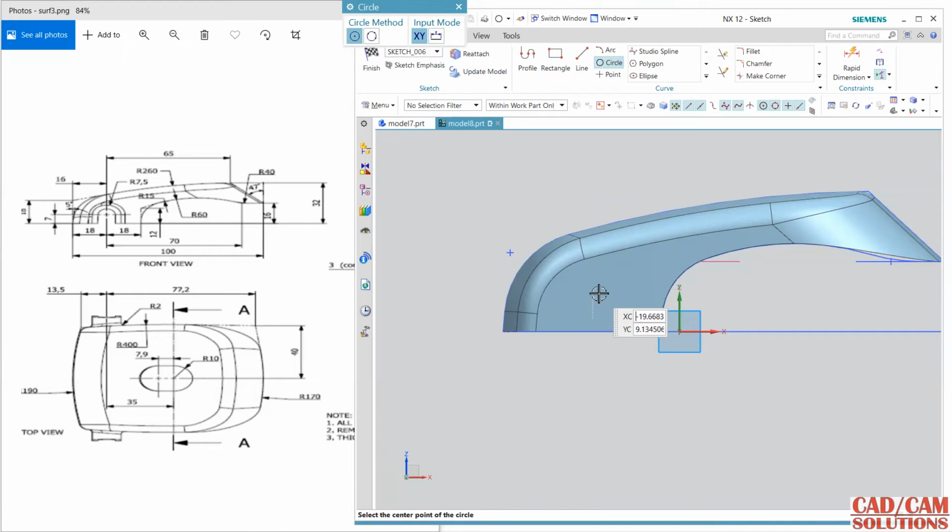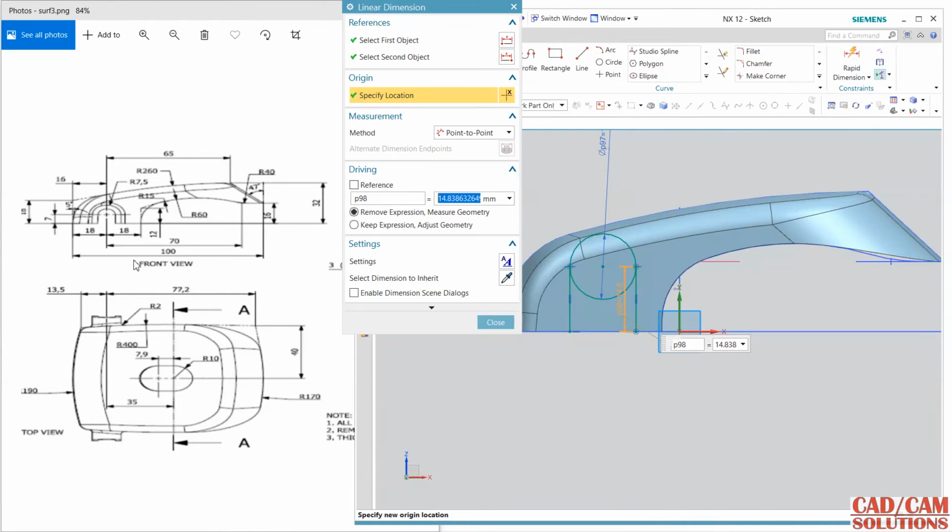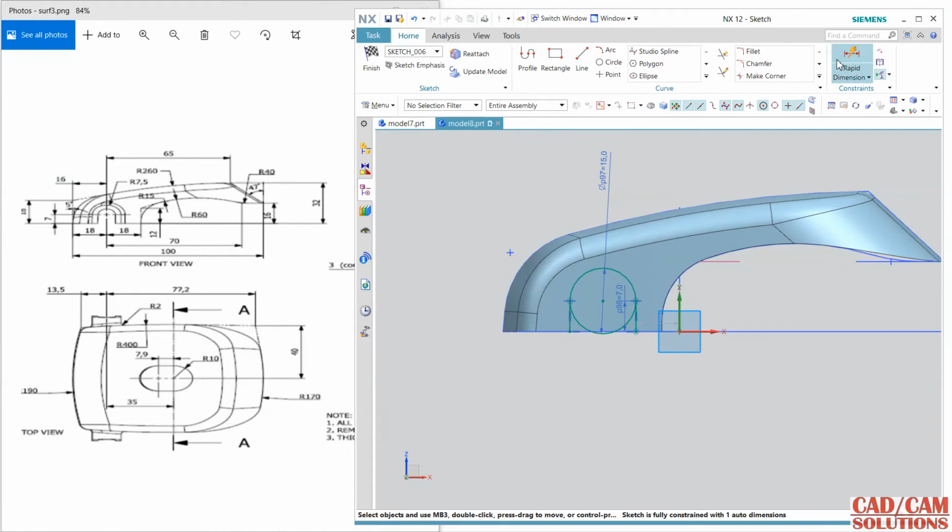Here I'm starting with the circle, and the circle is 7.5 in radius, so 15 diameter. Use this line again, one more line, select both lines, horizontally align and align with this horizontal axis. This gap is 7, which is given here, it is 7. Close, use this trim to remove this, and 18 from the outer edge.